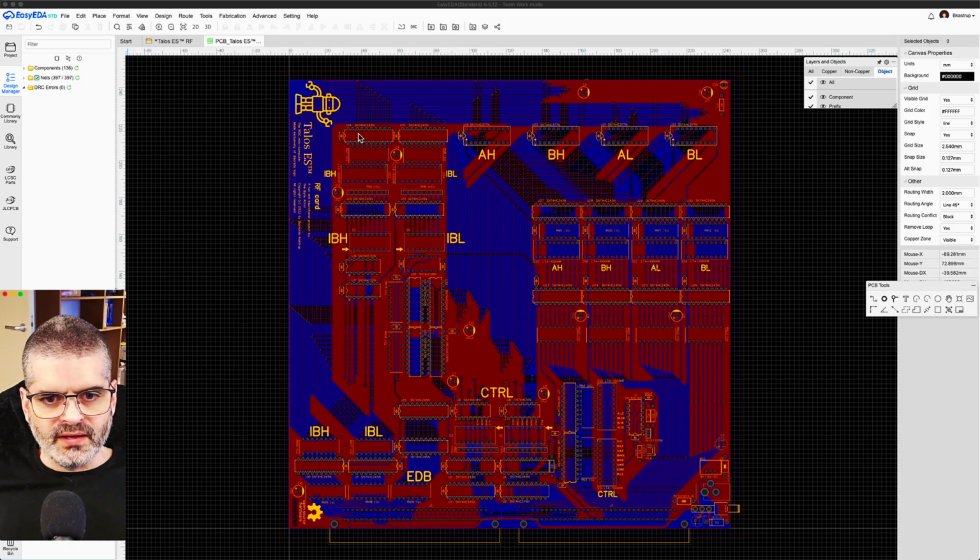Now, this here on this corner, the upper corner here, what we have, let me see. These are the LEDs, respective 1K ohm resistor networks and respective buffers that show the contents of the local bus, which is the segment of the internal bus in this card. And this is the local bus. You see these lines along the left side and the top of the board. This is the local bus.